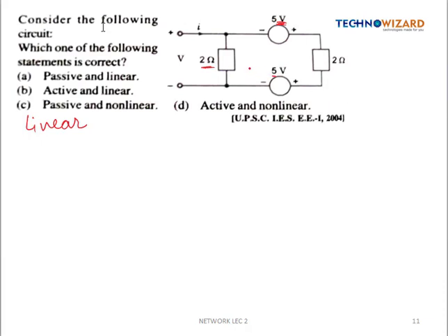So simply here current I is coming, now it will divide into two. Here some I1 current is coming and here I2 current is flowing, right? So if I apply the KVL in this loop, right, so it will be something minus 5 volt plus, this will be plus 5 volt, right?